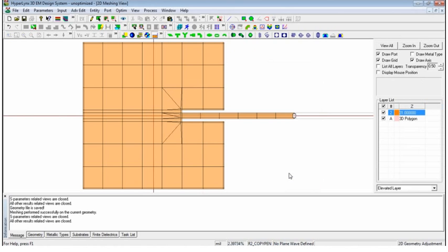Continue. So it will show how exactly my antenna is being meshed. You see smaller squares and rectangles. These are nothing but the individual elements which would be used for the simulation purpose. Okay. So the next task would be to simulate this structure. So if I go to process, simulate.